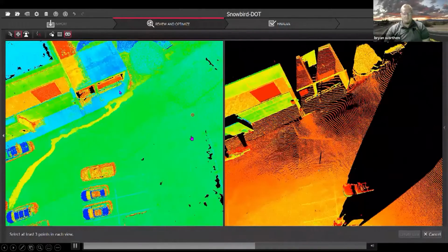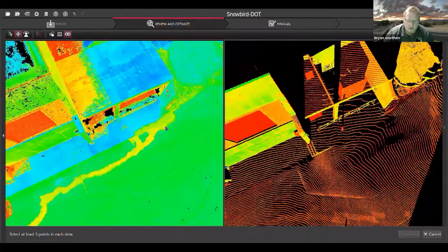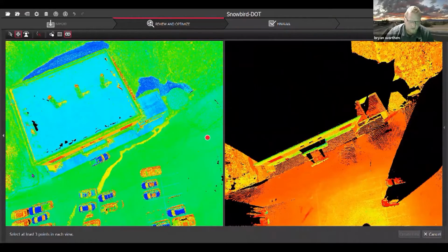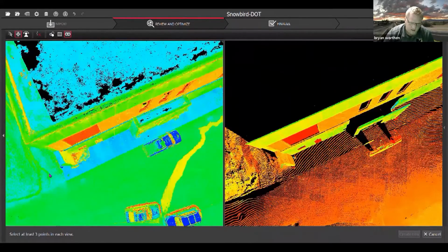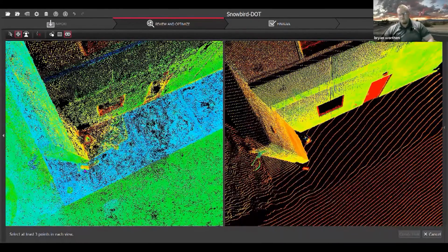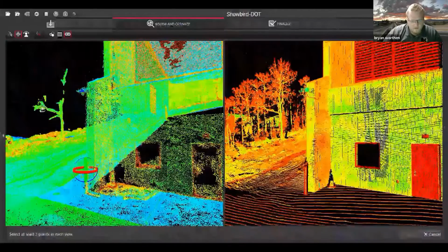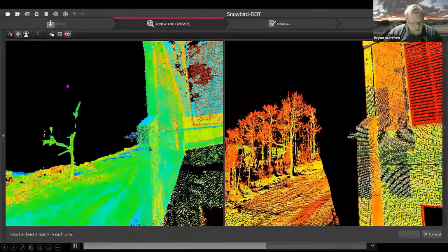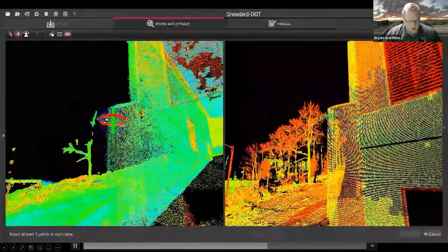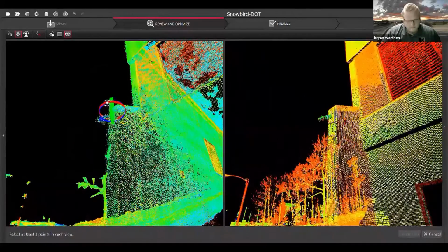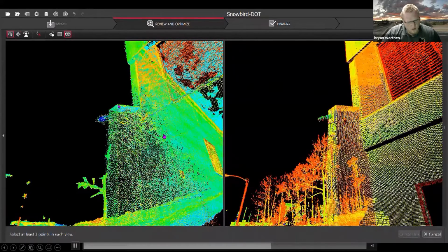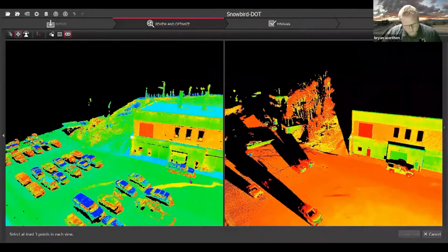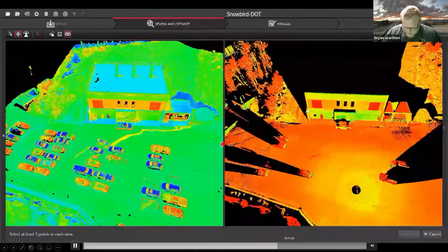Okay. So here's the split screen. I changed the view, so I'm looking at heat maps, and this is a pro tip. The heat map gives you more contrast, and it helps you to identify key points. So I'm looking at that concrete corner of the building as a good geometry point. I'm selected on one side, selected on the P40 data, and I'm going to move around and look for another point. Because we lost some time, I'm just going to skip ahead.